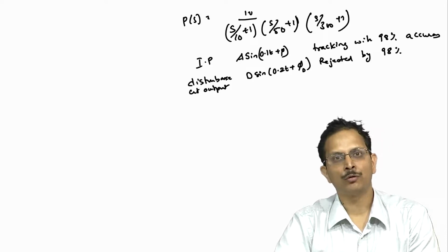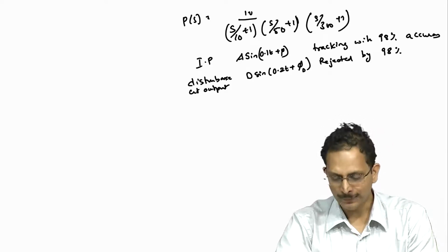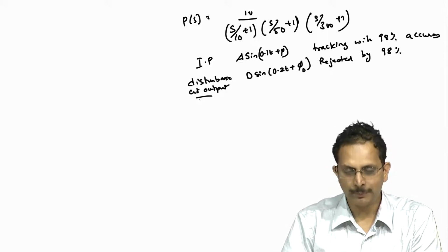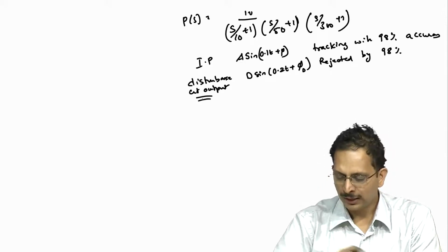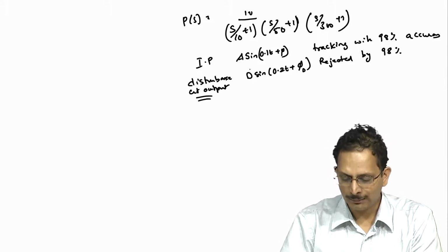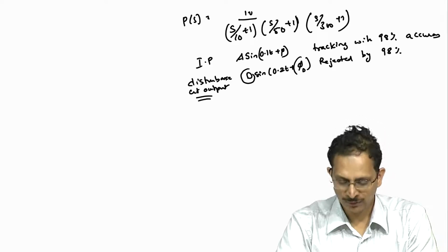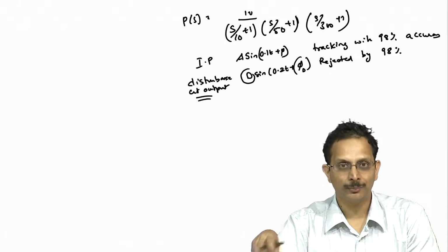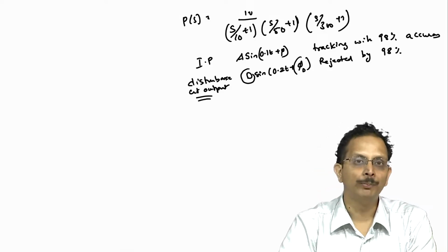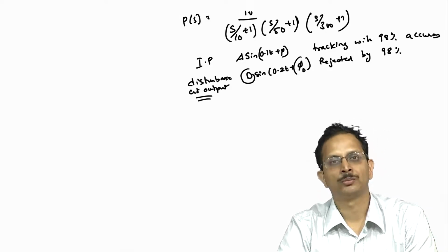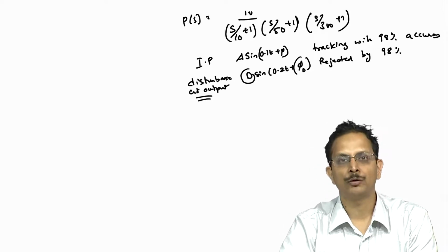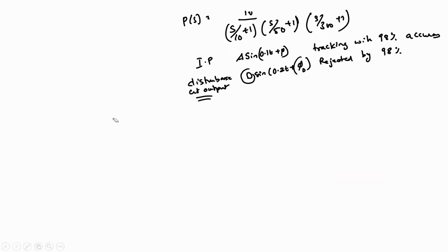So, to that extent therefore feedback control is not necessary, but there is a disturbance that affects our plant, and this disturbance has an amplitude and a phase, both of which are not known. Therefore, on account of the presence of this disturbance, we cannot employ an open loop based solution to this control problem, and one has to therefore employ feedback control. Or in other words, if we have this plant P, we know that this plant P has an output disturbance D that is afflicting its output.